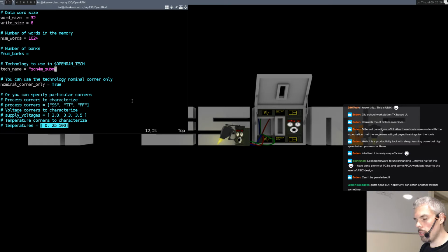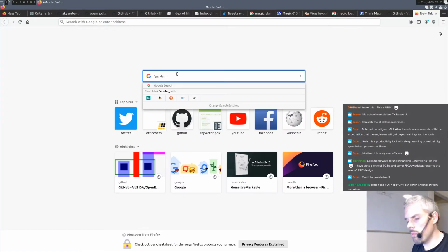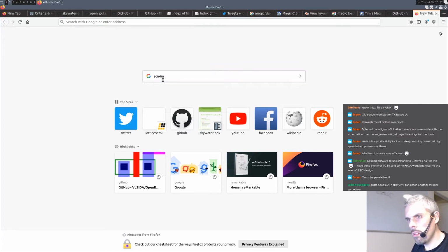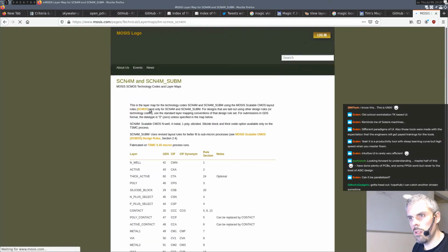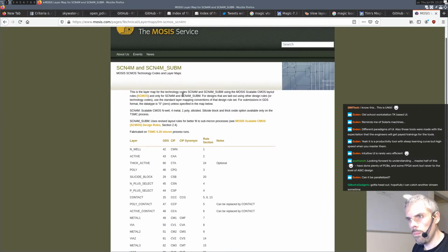Those have to be custom designed, integrated into OpenRAM as basic blocks, and then OpenRAM can tile them together to make a parametric RAM of whatever size you want. So at the moment, I'm using another process which is supported, which is a much larger process. I don't remember which process size that is, but I think it's huge. SCN4M CMOS layout.